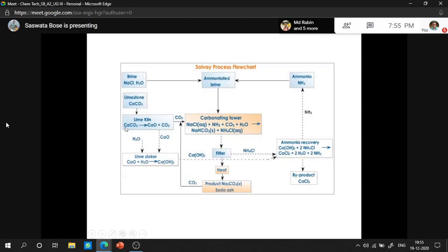In the lime kiln, you utilize naturally abundant limestone to produce carbon dioxide, and for the rest you need not add any cost. The ammonia is also recovered in the ammonia recovery section, so you need not feed ammonia gas or carbon dioxide to run the process. Now the filtrate liquor from the rotary filter is sent to the ammonia recovery section.